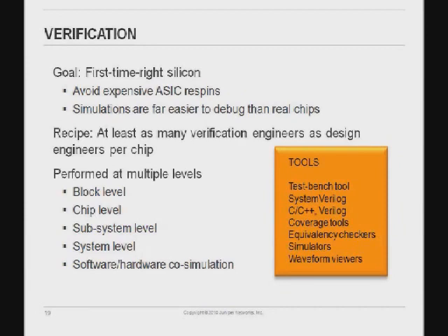So the recipe we have is to provide at least as many verification engineers as design engineers, and these days probably there need to be more. We perform verification at multiple levels: block level, chip level, subsystem level, system level, and we also perform software and hardware co-simulations so that the software can work together with the hardware before the hardware is available.